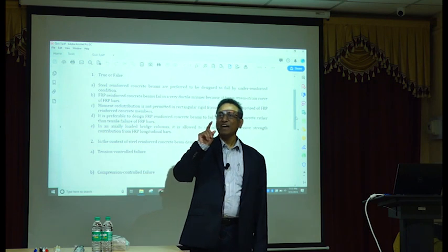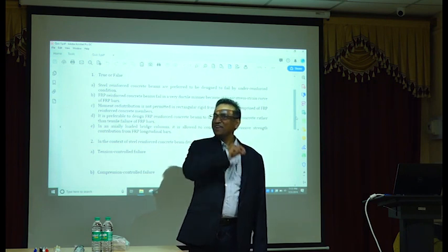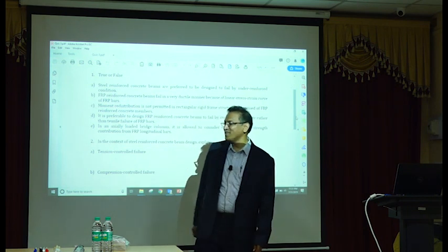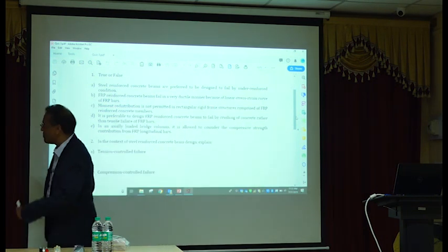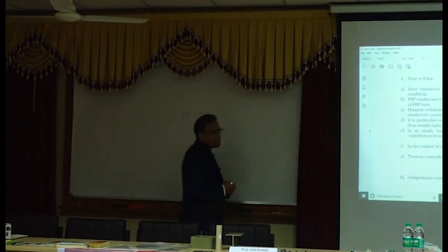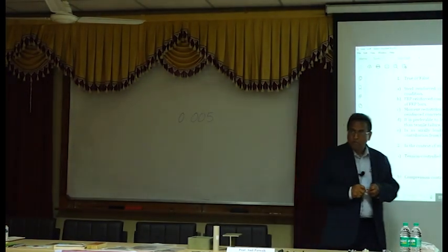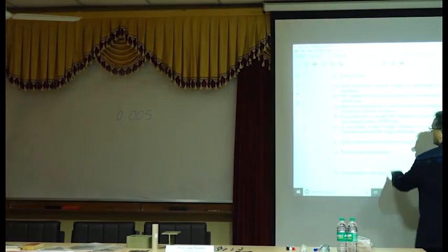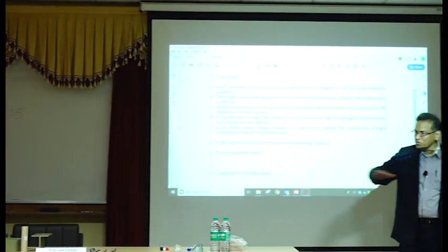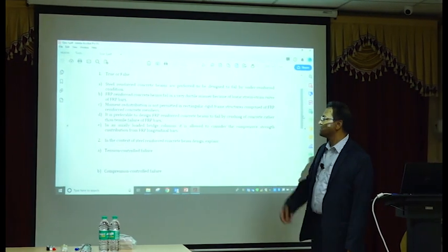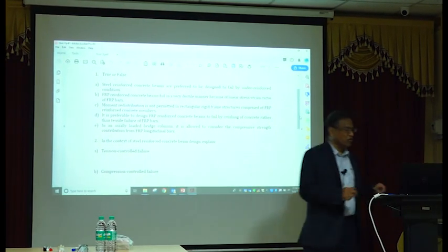Okay, but you did not tell me what the limit is. 0.005. That's very important. We need to remember that. And that strain is at the level of the bottommost layer of steel, epsilon t. So if my strain in the bottommost layer of steel is at least 0.005, then it is considered to be tension control failure.